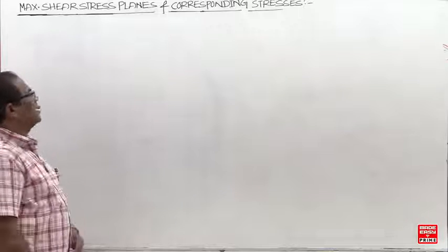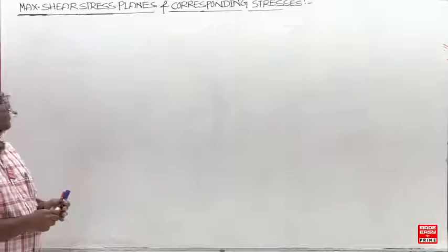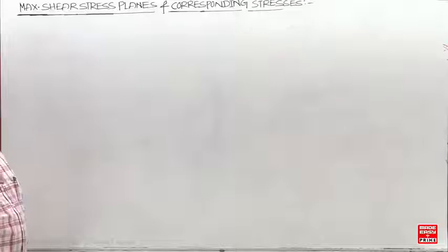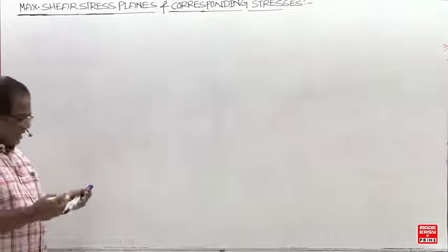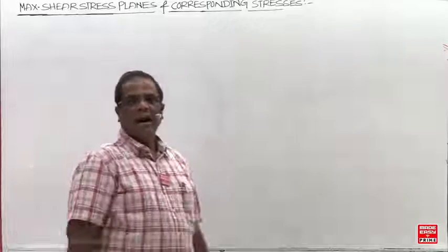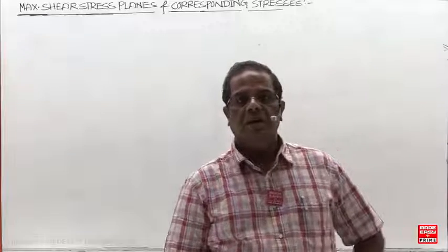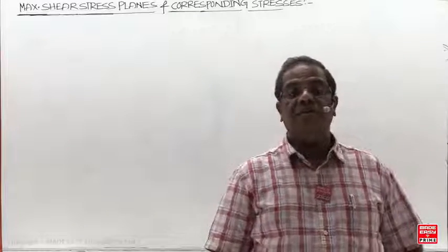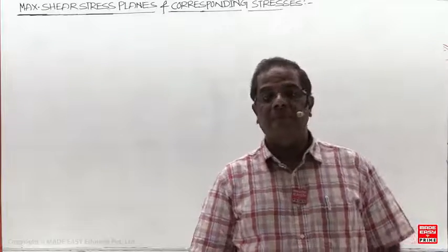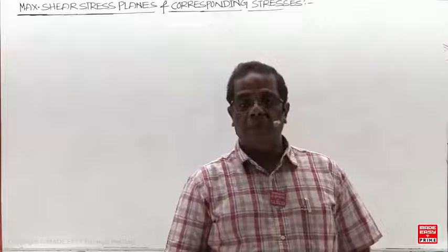So already you have studied these planes. Maximum shear stress planes are the complementary planes on which shear stress is maximum, but normal stresses may or may not be zero.